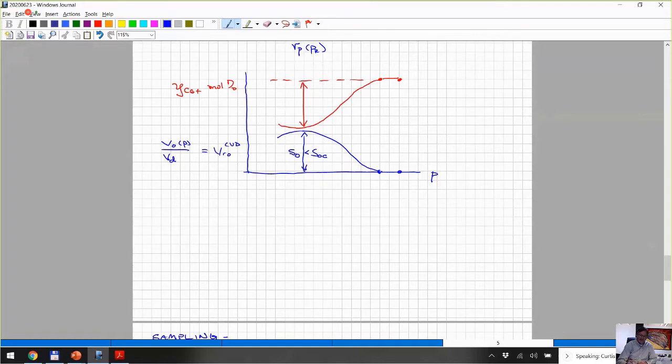Now if this data here is questionable, and often you see bad laboratory data, this data drops way down, unrealistically low. There's a bad material balance. So let's say that the data looks bad or unreliable, then you wouldn't use the data in the fitting. And then what you're left with is the liquid dropout curve.